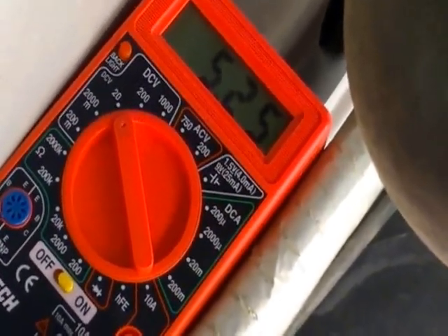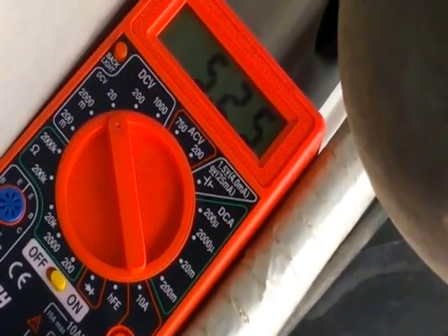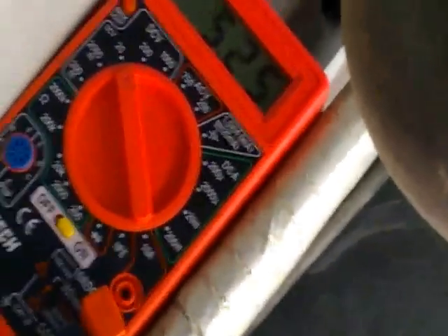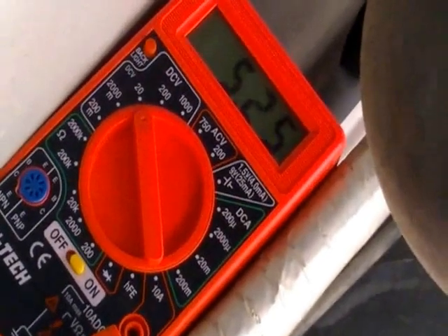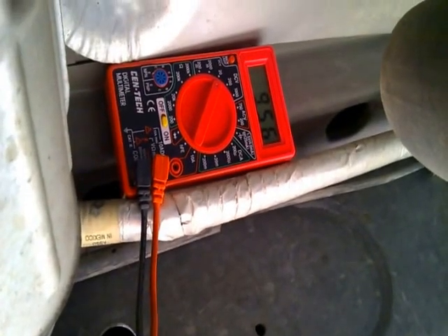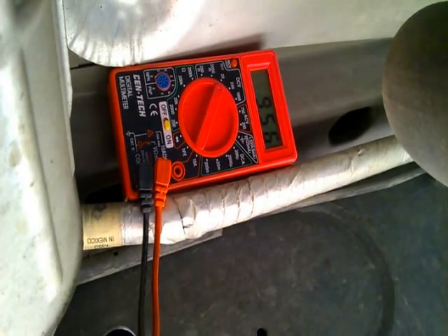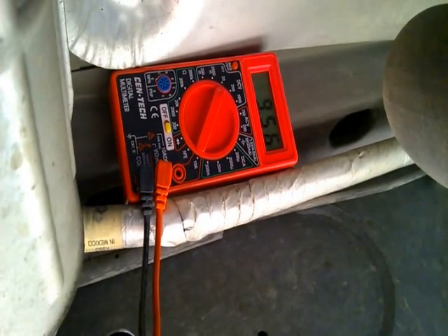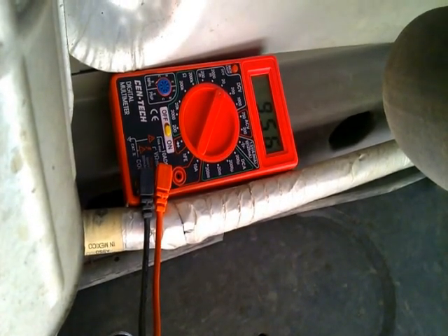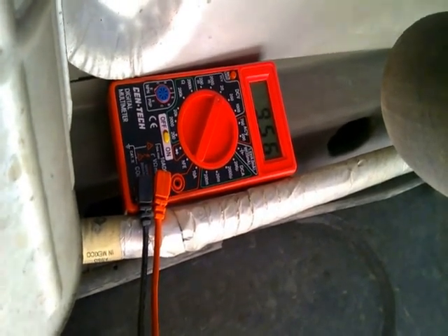Now, if I go back to the ignition with the key on, engine off, this 5 volts should jump to around 10 volts, minimum about 10 volts. So I'm going to go back to the ignition switch and turn the key on, engine off. Alright, I'm back at the voltmeter. This is with the key on, engine off. As you can see, the 5 volts jumped to 9.56. I think my battery is going a little low, but it's still within specs. Ideally, it should be around 10 volts, but 9.56 is still a good voltage.